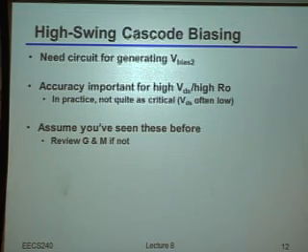It turns out that anytime you do these cascodes, you need some kind of bias voltage for the cascode itself, exactly to control that internal node voltage that we just talked about, that Vx. Okay? So there's a whole bunch of circuits you can come up with to do that. But I'm not going to spend any more time on it other than to mention a couple of important things. Basically because, as we just said, largely speaking, it's not super critical to get that exactly right, as long as you're close enough that you will get the higher output impedance at the range of VDS you're interested in.